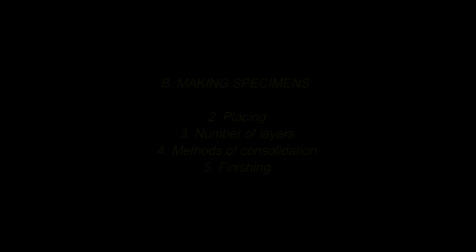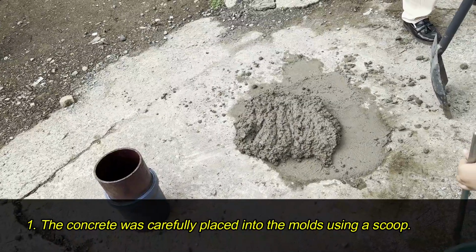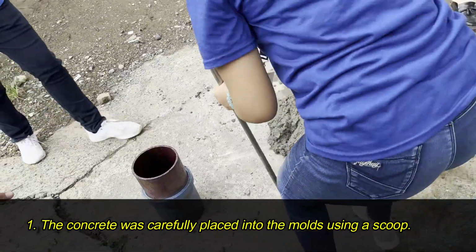The specimen was molded as closely as possible to the location where it was intended to be stored within the initial 24-hour period. The mold was positioned on a sturdy surface, ensuring it was devoid of vibrations and other sources of disturbance. Number 1. The concrete was carefully placed into the molds using a scoop.